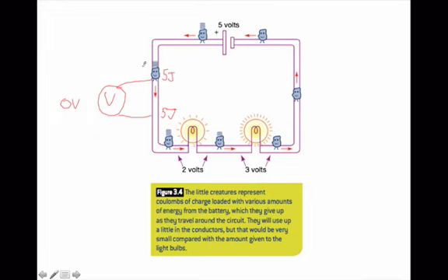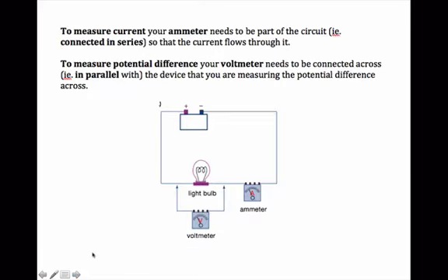So I mean, we could have 1,000 volts flowing through here, and at this point it would also be 1,000 volts. And so therefore your voltmeter would show 0 volts even though you have a huge voltage running through here and potentially a massive current. So remember, voltage is just telling you the difference between 2 points. And as you can see, the voltmeter does need to be connected up in parallel, which is what we've got here. So voltmeters always need to be connected in parallel.